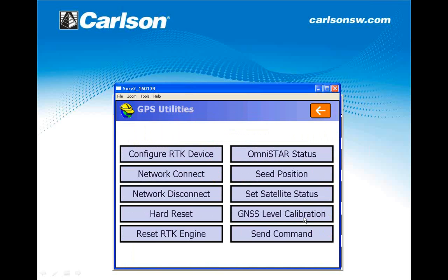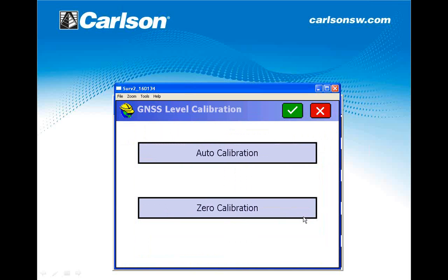We are even doing a one-point check to prove the calibration is good on tilted poles. All those features will be coming in version 5, already working for some units like the StoneX ST, but we are doing the final refinements. Okay, so let's go to level calibration. Zero calibration is not very good, I would say, because you need to be in a horizontal place.